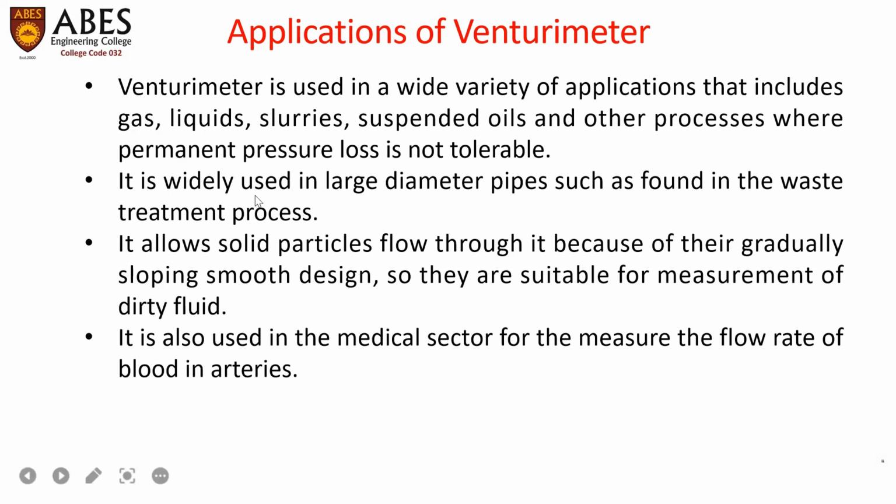Second point, it is widely used in large diameter pipes such as those found in waste treatment processes. So wherever the waste treatment process is going on, we can apply the Venturimeter at the large diameter pipes. It will be helpful to calculate the flow rate in that case.